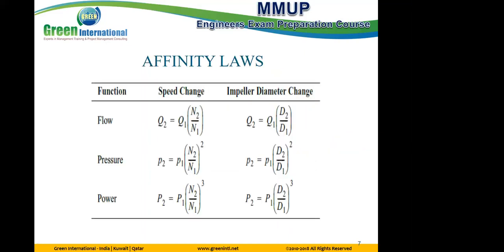Okay. Affinity law. One of the equations that also comes many times in the exam, a lot. Sometimes it comes for a pumps problem, sometimes for a fans problem, according to the application. To make it easier to remember, the speed equation is more important than the diameter one. The relation to diameter is not as important as the relation to the speed, N. But it's no problem if you remember one, because the second is the same, typical.